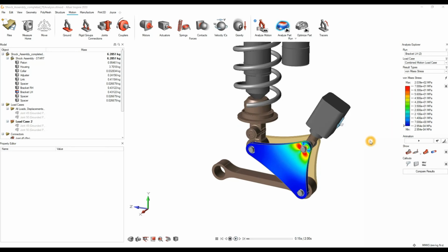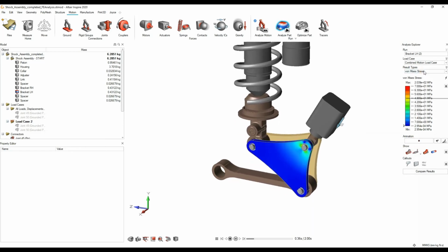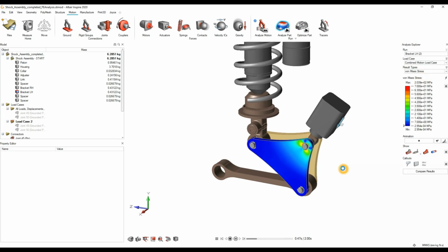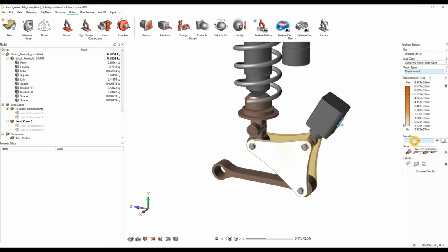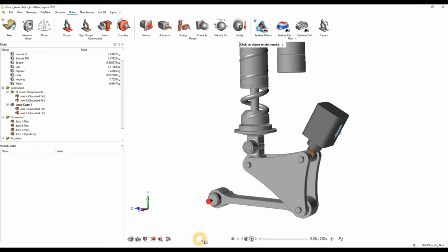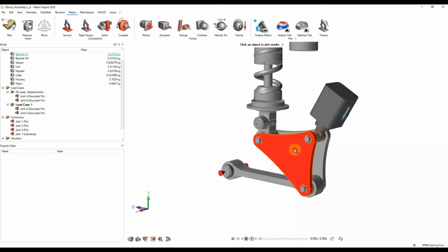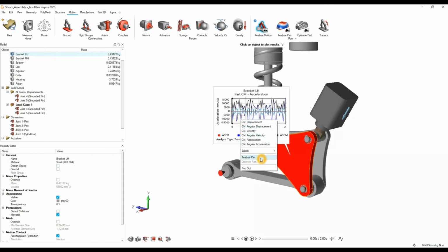As you know, after conducting any type of structural analysis, we now know the stresses that go through it, and the displacements that it also goes through. What's nice is that we can then take it through for structural optimization as well. So if I head back into my previous model, if we were to click on any of these parts, you can right click and do analyze, but you'll see that underneath, the optimize option has been grayed out.